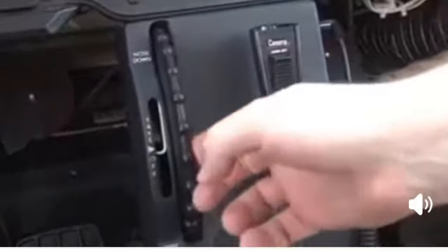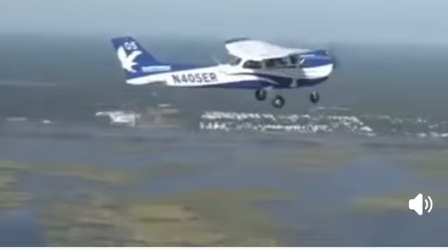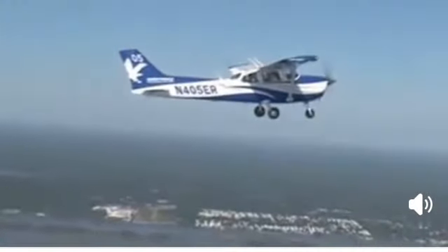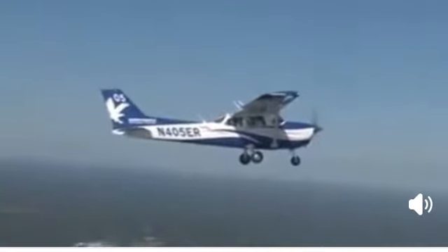The elevator trim is typically controlled through a wheel inside the cockpit that is labeled nose down or nose up. As the pilot moves this wheel, the cables will adjust the elevator trim tab, which is located on the aft or back end of the elevator. Usually during takeoff, the trim tab is in its neutral position, which means it is just about flush with the elevator. As the pilot climbs, however, he or she may trim the airplane to help relieve control pressure and prevent pilot fatigue. If he or she wants to climb at a specific airspeed, then the trim can be adjusted to maintain that airspeed.